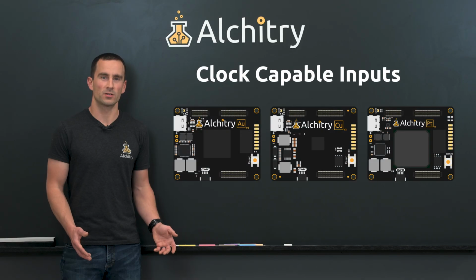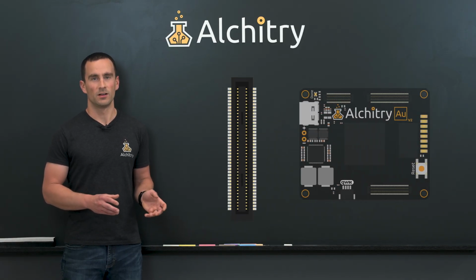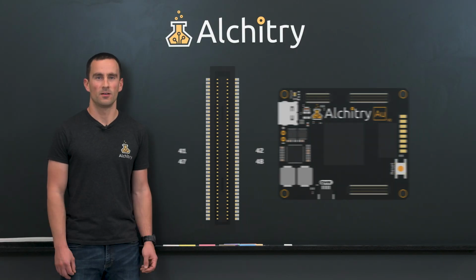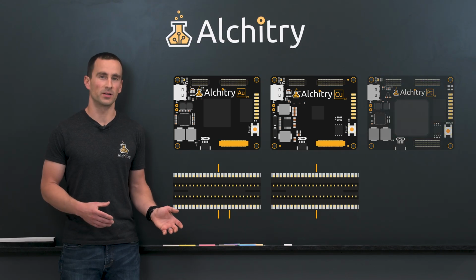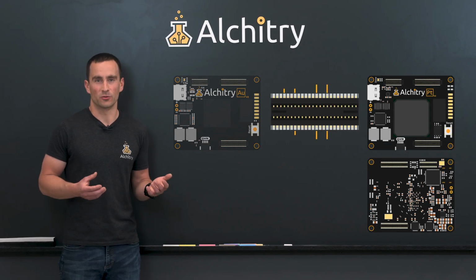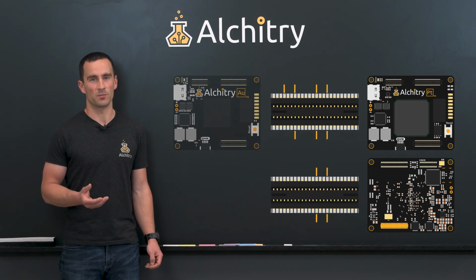On the Alchitry boards, clock-capable pins are placed in the same places on the headers. That is, pins 41, 42, 47, and 48 on each header. Bank A is always fully populated. However, Bank B is partially populated on the CU and AU. The PT, with all its extra I/O, has 3 additional clock inputs on the top side bank B and a fully populated bottom side bank B.